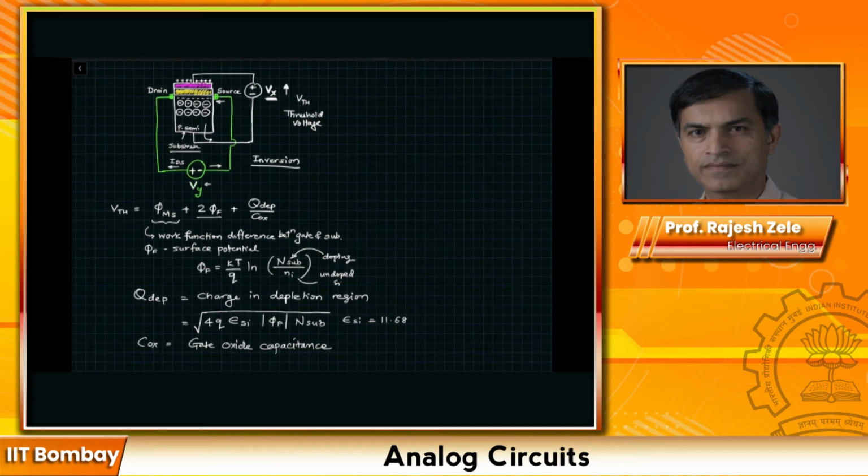Holes in the p-type semiconductor would get repelled from the interface, and it would be easier for us to get an inversion layer under the channel. So reducing the thickness of the oxide region, by which we would increase Cox, would result in a reduction in VTH.